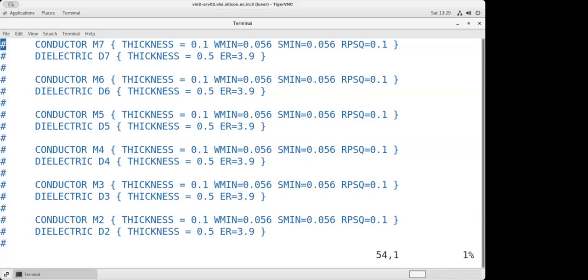Now this is that particular metal 5. Here you will see metal 6. Now what is important in the metal? Let's try to understand that. Width. Am I right? That is something the foundry is going to provide you. Like, if you want me to design a wire with a width less than this particular minimum, I cannot design it. Here we are talking about electronics, but in a fab, everything is mechanical and chemical. They don't have anything with respect to electronics. Everything is mechanical and chemical.